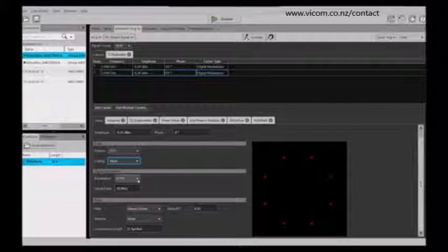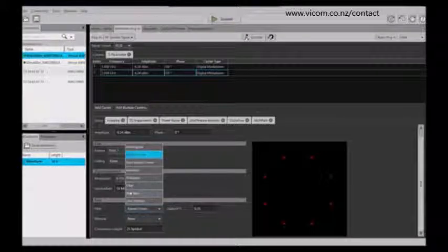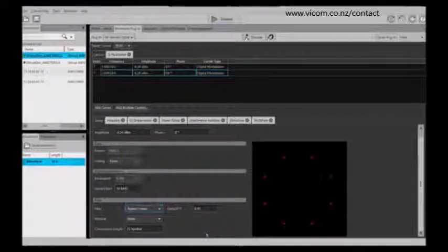So you can also pick, of course, your symbol rate, and this would be for each waveform that you've got selected. So right now I'm working on this particular waveform. If I change the frequency here, it would be shown highlighted up in the above in the actual index of waveforms. You can specify your filters. Again, you have quite a variety of filters that can be used for your modulation, and also your alpha values can be selected here.